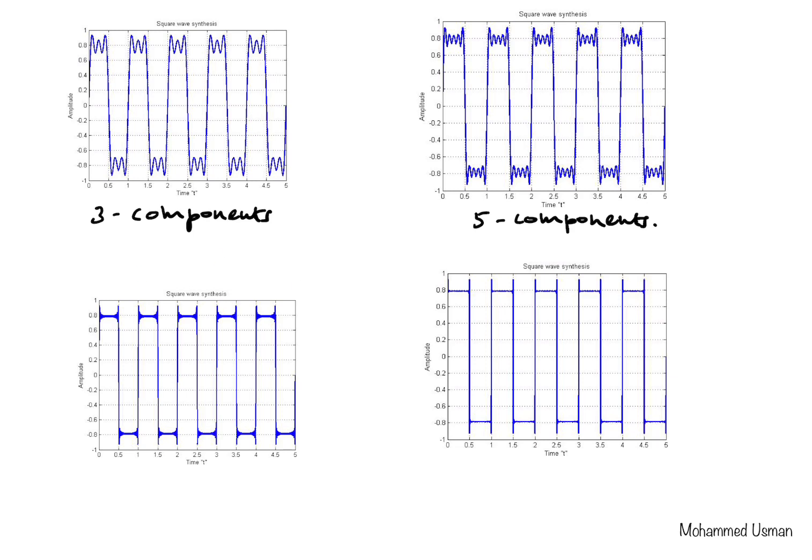And this waveform on the bottom left here is the square wave generated using 25 components. Again, we see now it is much better represented, and the ripples have become much smaller. Although the frequency of the ripples is high, the ripples have become much smaller, and the vertical line is also much straighter in this case.